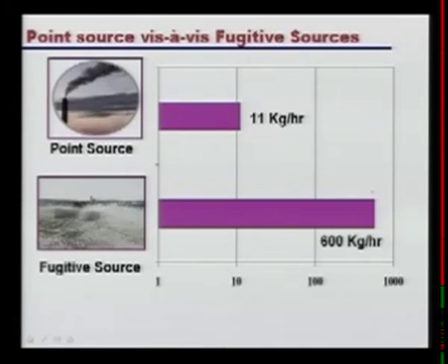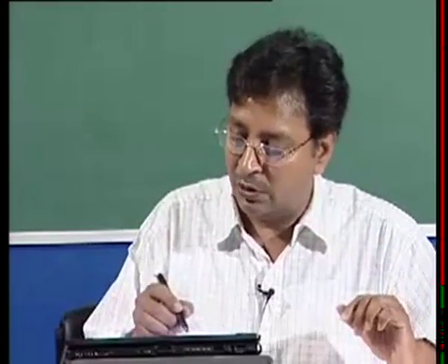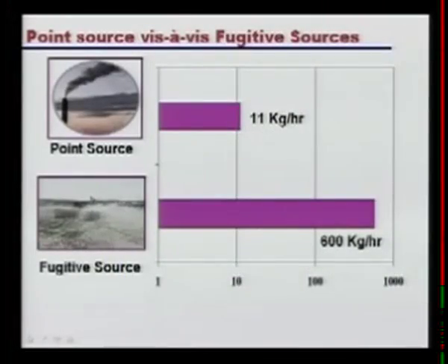Finally, interpretation is a very important part, and a person gets a feeling as to which source is important when you show things in a relative sense, because absolute numbers sometimes people don't understand. For one study that was done, you see here the regular source from the chimney was very highly controlled, with lots of money spent on ESPs and bag filters, and no one was there to take care of the fugitive source.